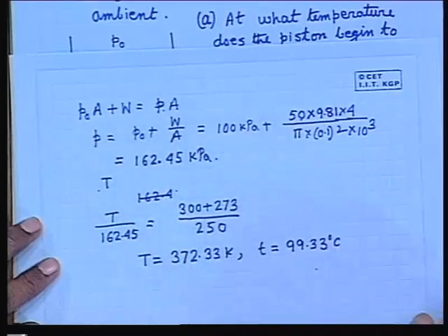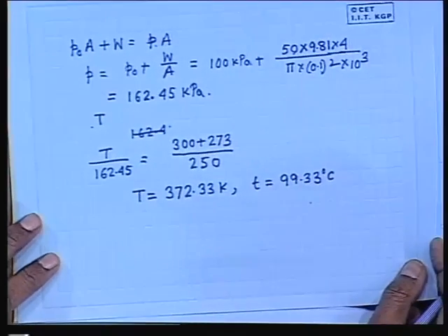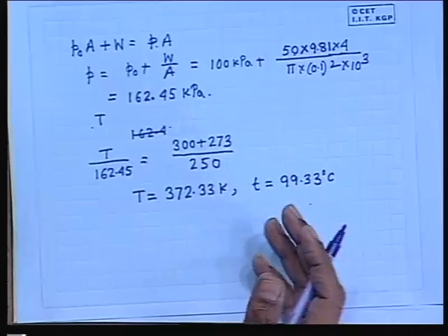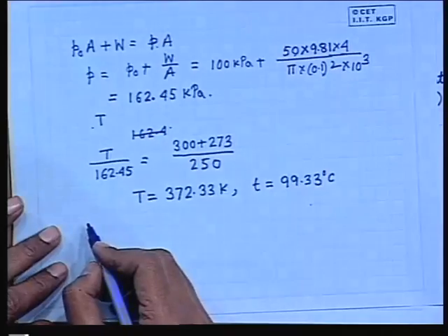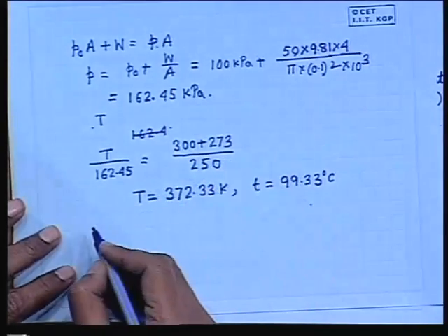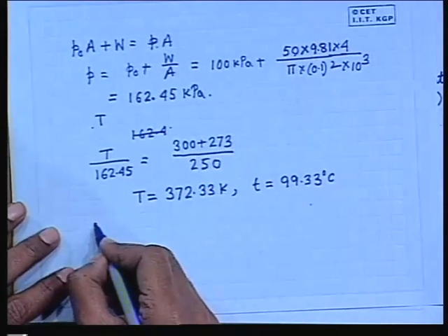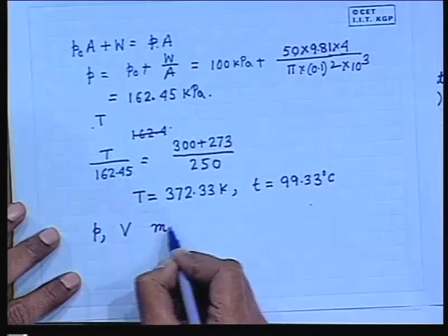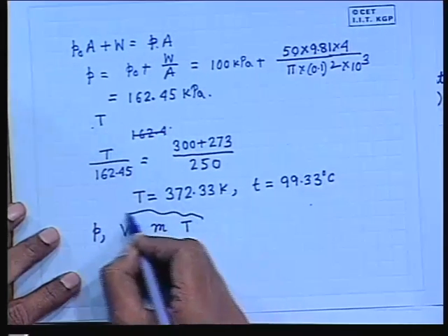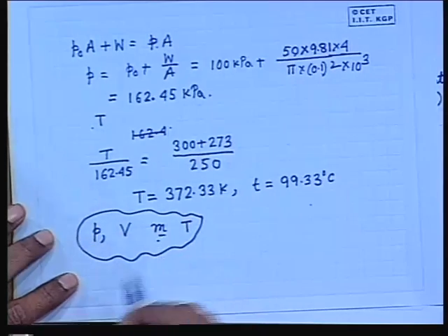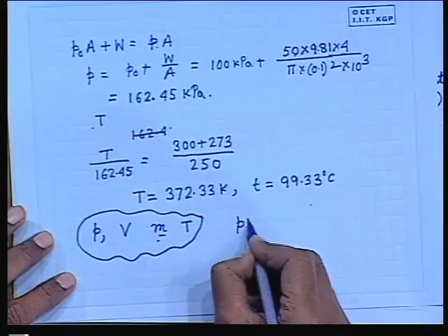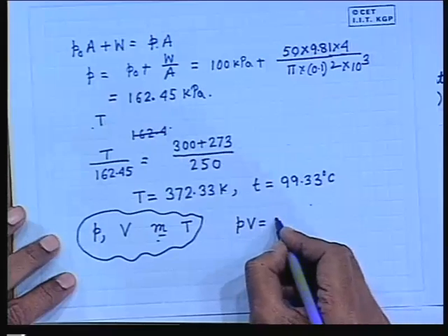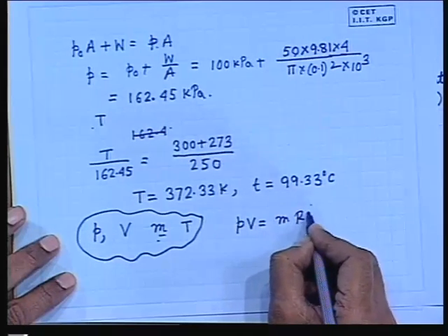Now, where from you got P1 by T1 is P2 by T2? Volume. But you are not supposed to know now, first law. So, I tell that sometimes it will be given. If it is not given, then for air, I recapitulate the earlier things. You always know that if P is the pressure, V is the volume, M is the mass and T is the temperature of a certain mass of gas M, then for any ideal gas, this is the relationship PV = MRT.